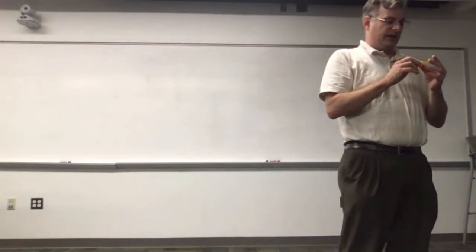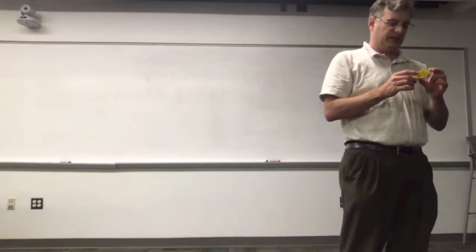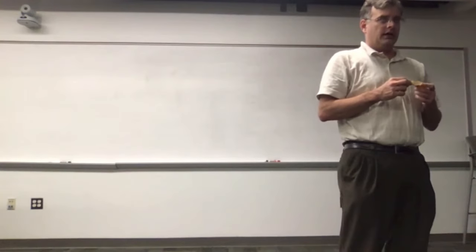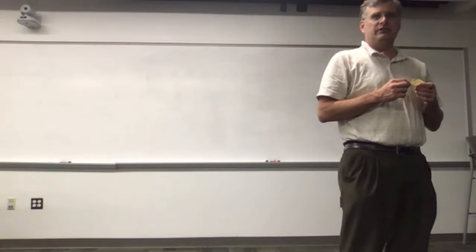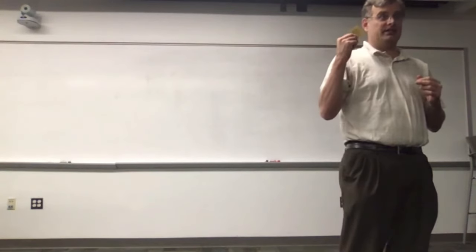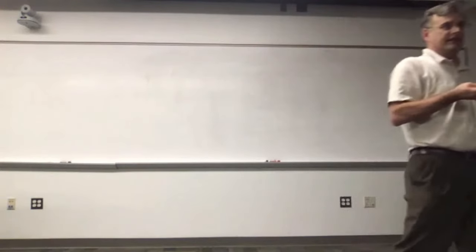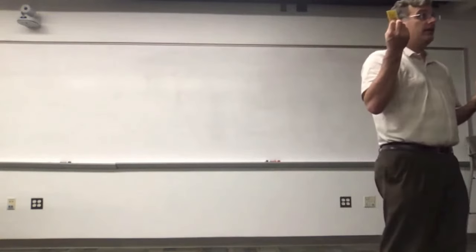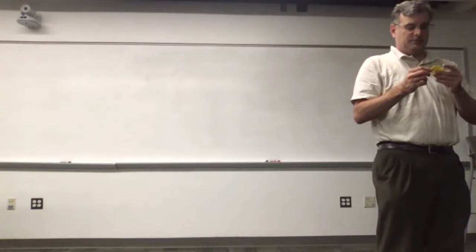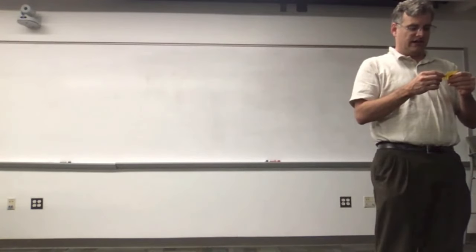An engineer buddy of mine, Albert Liu, made this antenna. It's a beautiful design, 10 dBi of gain, which for this antenna size is pretty good. You might only be able to do maybe 7 dBi of gain for a regular Yagi antenna with 3 elements on it: a driver, a single reflector, and a single director. Here you get a few more dB because he bends it in a particular direction. Again, this is an antenna that would only be designed if you had a numerical package, because this becomes more complicated than even the regular run-of-the-mill Yagi antenna.